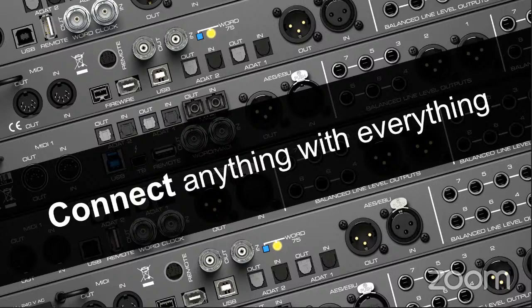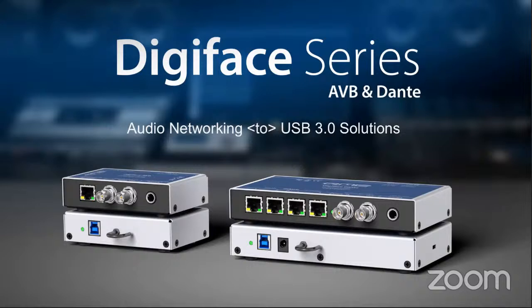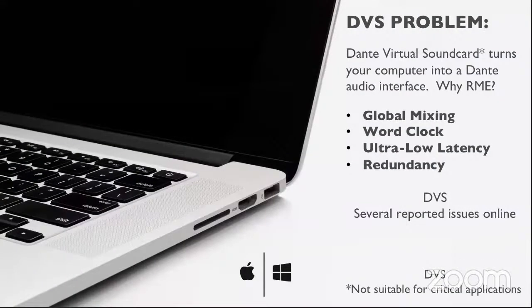Now, one of the key things of technology you're going to want to know about, and this goes back to the Dante Virtual Sound Card discussion I was having a minute ago, is the Digiface series from RME. They make essentially audio networking to USB 3.0 solutions. Whether you're working in an AVB network, you have a Digiface AVB. If you're working in a Dante network, you have a Digiface Dante. Now, we go back to the Dante Virtual Sound Card challenge. Some of the advantages that these offer over Dante Virtual Sound Card is word clock, global mixing, ultra low latency, redundancy, etc. All of that is possible.